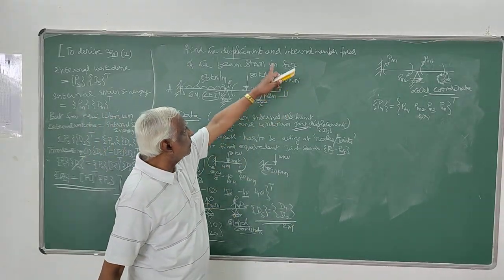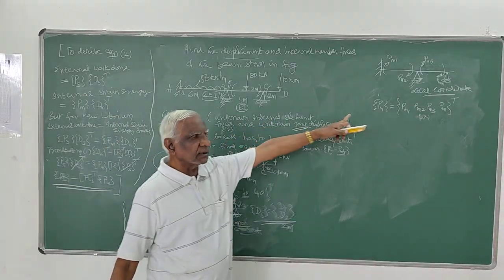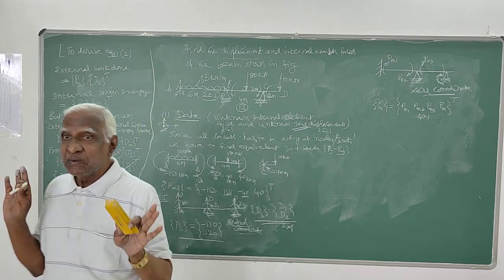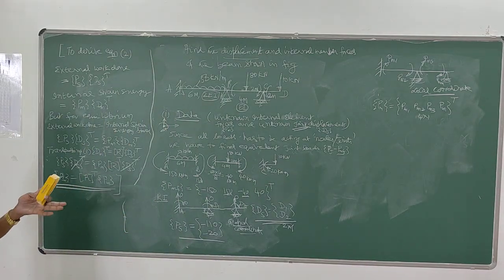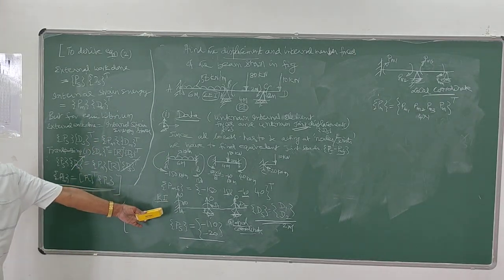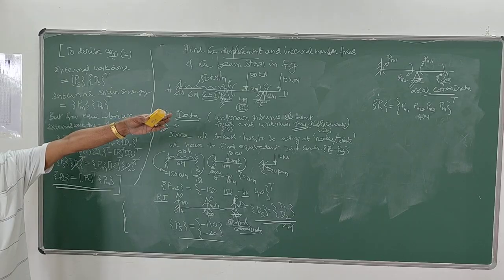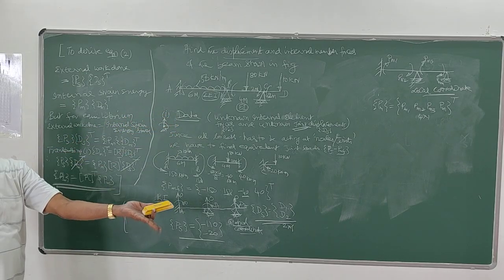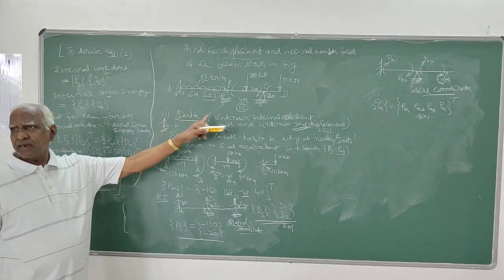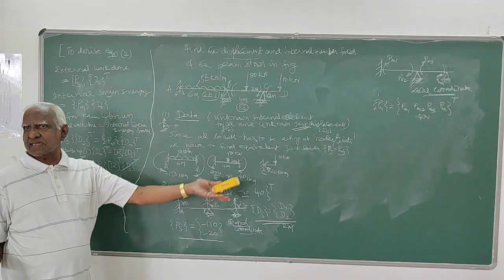Global unknown displacements, the joint displacements, are DS; unknown internal member forces are these. Correct? This much data you have to prepare. These are all only basic things. You need not waste this much time. Straight away simply write global coordinates, local coordinates with kinematic indeterminacy and static indeterminacy. What are the internal forces to be determined? That's static. This is kinematic. That's the first step. You have to get the data by determining static and kinematic indeterminacies mainly.